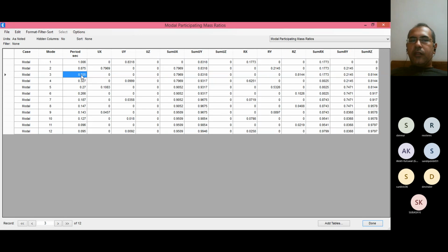So you need to increase the thickness of your element so that the J value increases. When the J value increases, the stiffness in the torsion direction increases and your time period becomes lower. So the mode will shift downwards. If the building is more flexible in torsion, then mode 1 or mode 2 can become torsion, which is not allowed by the code. So just by increasing the thickness of the elements, you are able to bring the solution as per the code.